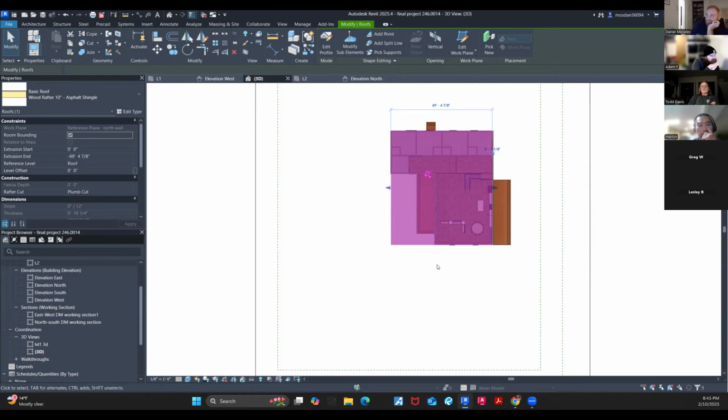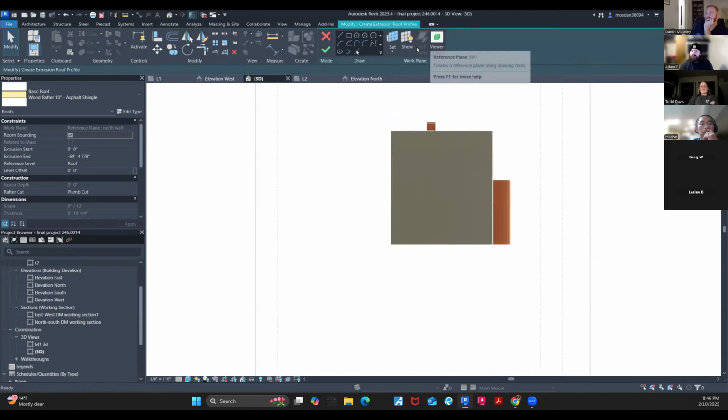Or we can click that vertical button. So up in the ribbon, there's a button right next to where it says edit work plane that says vertical. Keep going to your right. It's that third button from the right-hand side in your ribbon right now. Not in the tab. You're in the right tab. So just move. Keep going like 3 more inches. 2 more inches. Keep going right there. So click that vertical button, and we can now create an opening in the corner.